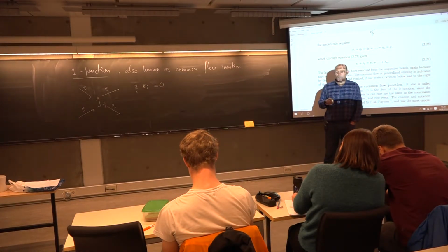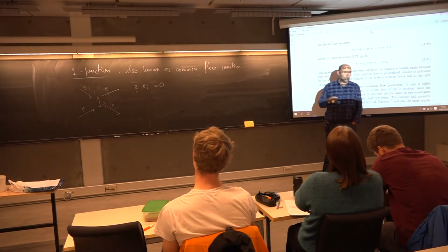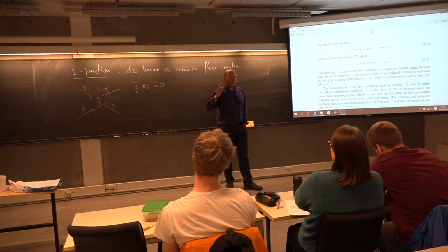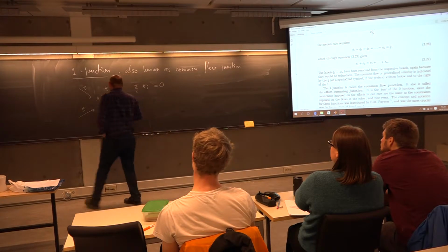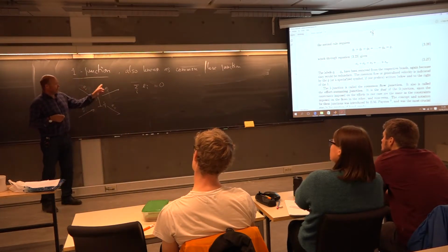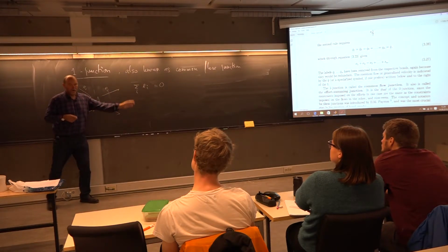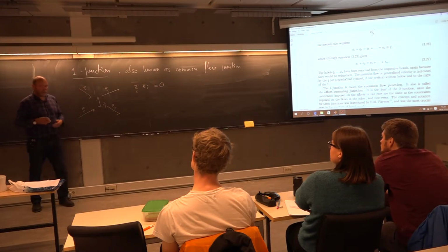Algebraically, this means that when you have a one junction or a zero junction in your bond graph, they will result in one algebraic equation. So you have the summation rule: around a one junction, the sum of the efforts has to be 0. Or around a zero junction, the sum of the flows has to be 0. So it's just one single equation that comes out of this.